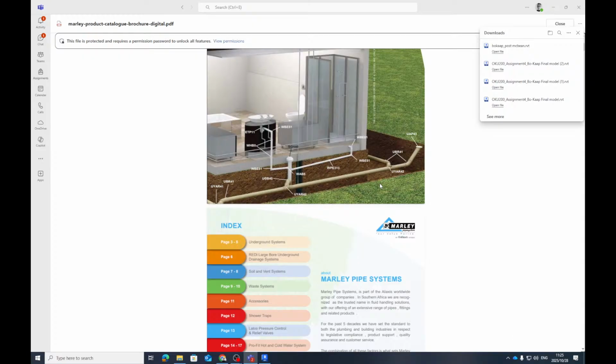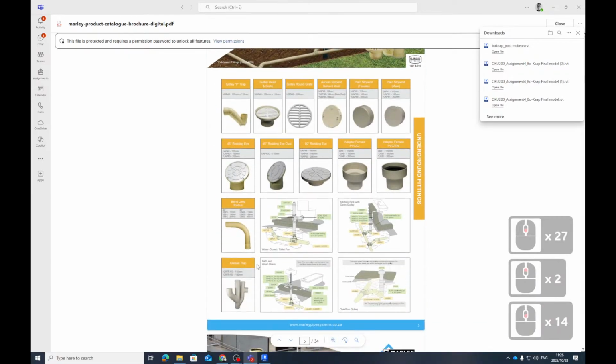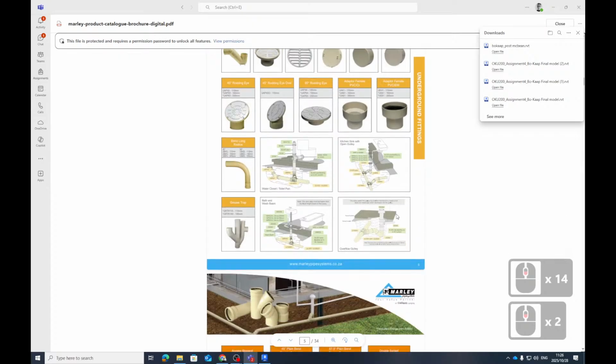You can have an RE, rodding eye, or cleaning eye, they're the same thing. Then your toilets, and that goes up to the ground because you have to rod it. Then it goes underground. Then your toilets start. Now, I would connect that one. That will connect into there maybe. This can connect in there, then go in. There is one of a bathroom here. If you keep going down, you'll see they even have diagrams of how it all works. Oh, that's actually nice. Toilets sometimes, you see how they connect into a stack? So your toilet is already a stack. They all connect into the stack and then connect to the sewer. Oh, okay. So here you're going to have a WC.